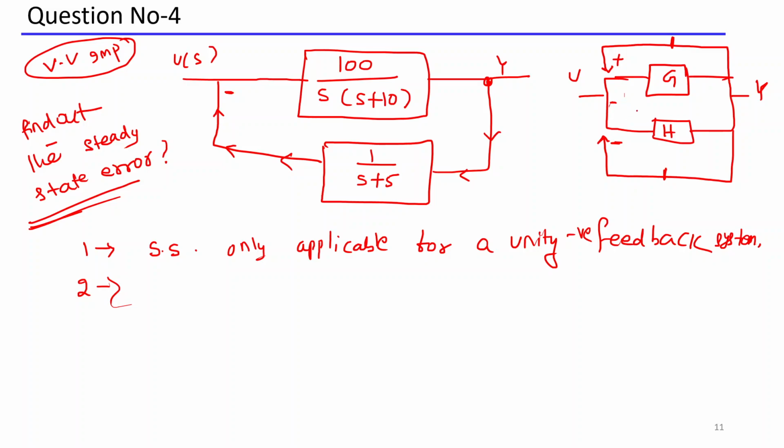So first, forget about all this. You understand that you have to add one positive feedback and one negative feedback. So first tell me, for this question, what is the transfer function Y by U? Already calculated in the last slide. This is G divided by 1 plus GH, right? I told you in the last class how to directly find out the transfer function.